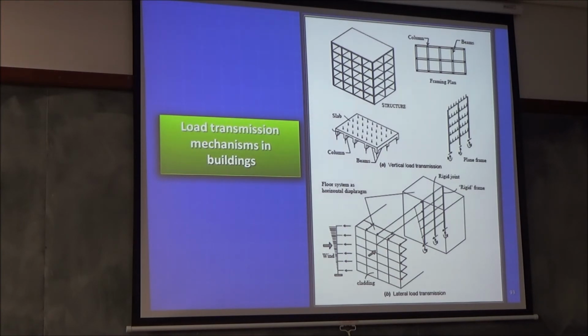Imagine you're the frame and someone's trying to push you. Because there's an infill masonry wall right in front of your eyes which you are not willing to look at. This frame has no masonry wall. So when you push the frame, you have to also push the wall with it, and the wall is not easy to push. The wall is a little rigid. The wall will resist it, and the stiffness of the frame can even be double.